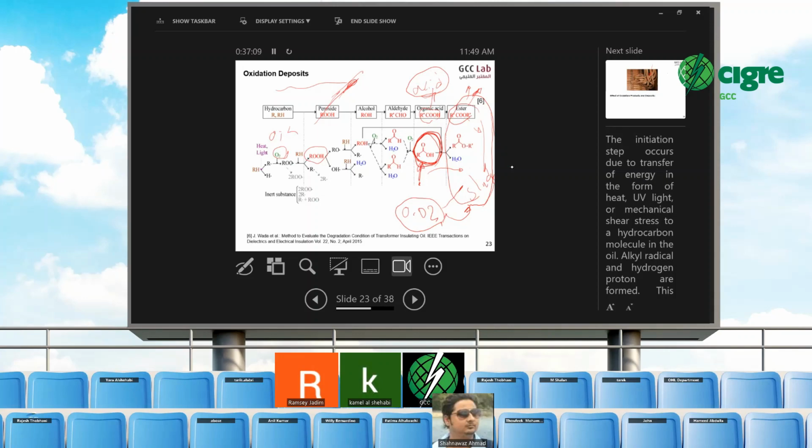Just to add to this point regarding the cable box oil analysis, it is very important to know the type of bushing that you have inside the cable box, if it is an oil communicating bushing or not. If it is an oil communicating bushing, then the oil between the main tank and the cable box is communicating together. This is a very important point, even if you have a separation in the conservator tank and the piping. I found that the cable box oil analysis is very important and very effective.